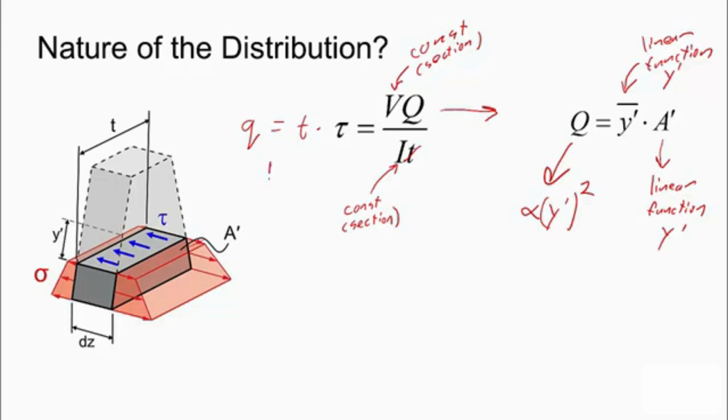So if we then plotted from our neutral axis a distance of y, and this was the periphery of our beam, it has to be 0 at the outer portions because the entire normal stress distribution will produce 0 resultant, and it's going to vary parabolically to a maximum at our neutral axis.